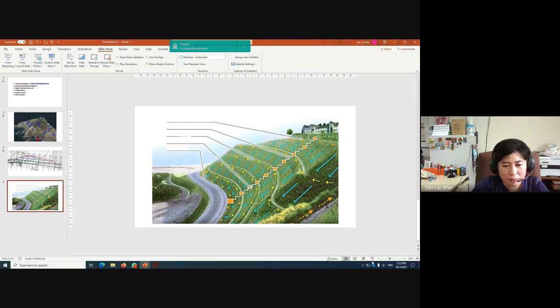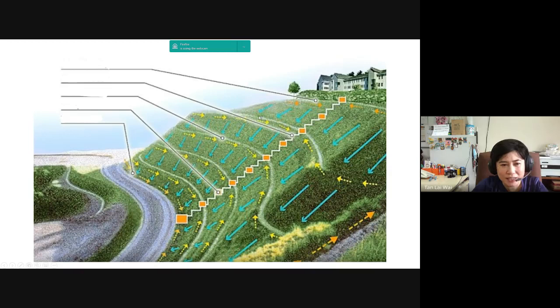Now, what I was explaining just now, here you have the bench drain. When the rain falls, it only caters for this drainage area, because you already have the interceptor drain that will cater for the upstream land. Another bench drain, only this part. Of course, this is a cascading drain, but it doesn't matter. We are not looking at that cascading drain. So far, okay, guys?